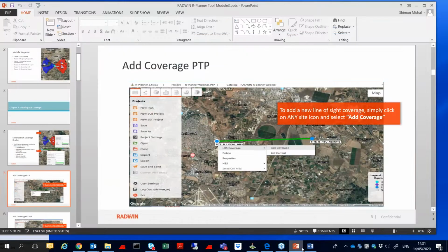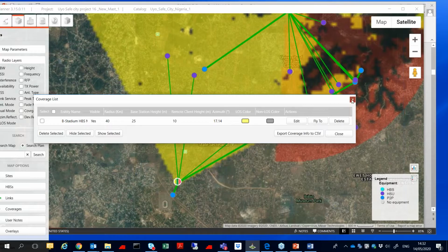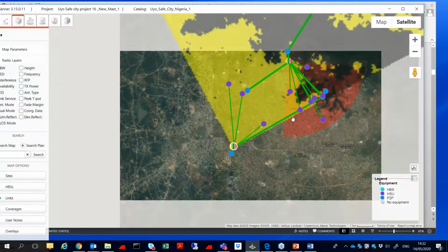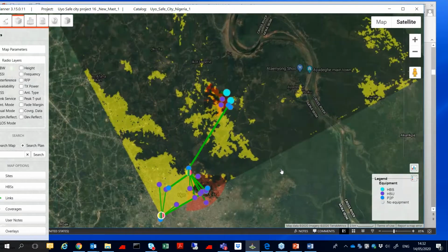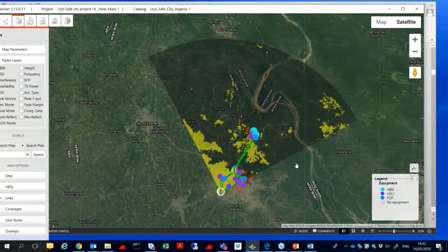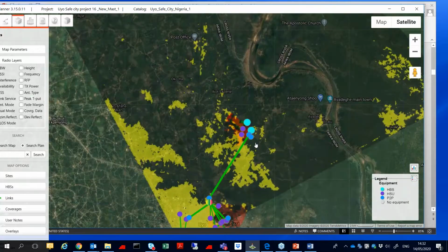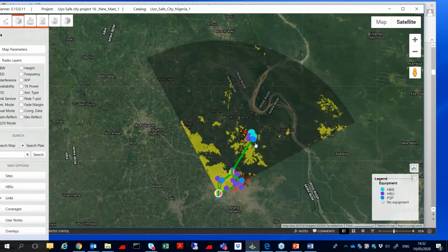I can tell you honestly, the longest distance that I did in point to point is above 100 kilometers. Many times I need to split the 100 kilometers to 2 links of 50 kilometers, but you can achieve a very nice throughput. And you can see that probably in long distance, you can have terrain obstacles, topological obstacles.